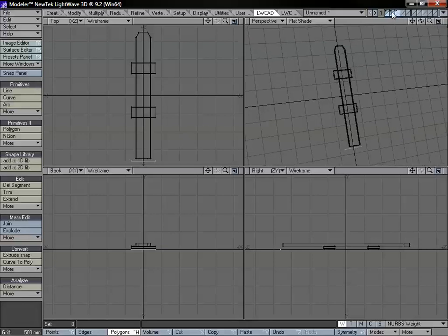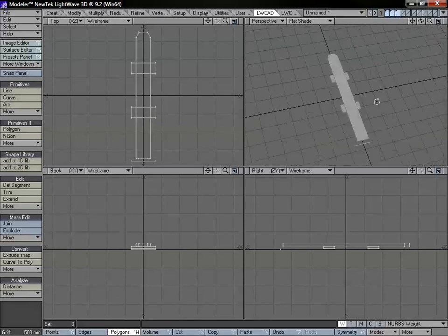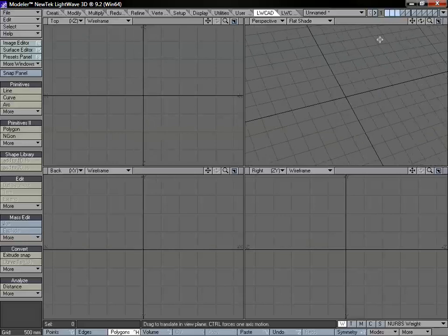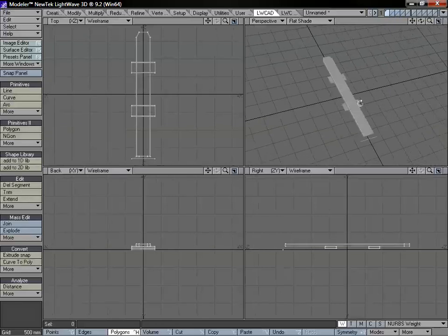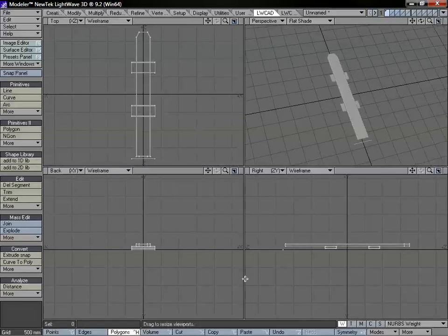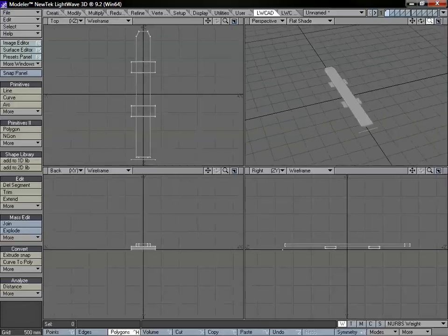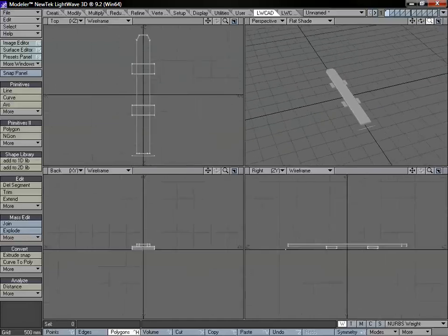So now what I want to do is just select all of these in the same layer, and I'm going to hit Control and X to cut, and just select our first layer and then paste that in there using Control V. We also have the copy and paste options on the bottom as well. And if you want, you can define your surface for this.